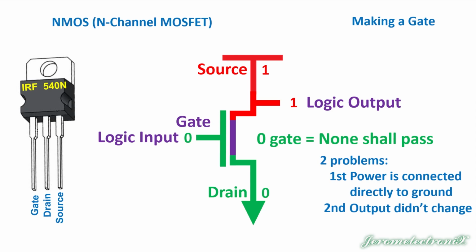See, what happens is when you connect power directly to ground, there is no resistance, which means the electrons can flow as fast as they want, faster and faster, and what they do is they collide with the different atoms on the inside. They release a lot of heat. That heat builds up, and there's no control of the heat, so eventually it ignites things or melts things or destroys things or whatever heat does to things. So the solution to that is to slow down the flow.